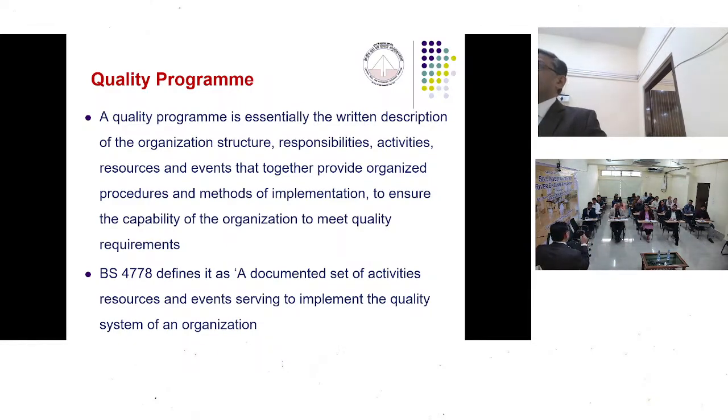At that time you are not going to consider that 1.76 or 1.75 or 1.77 are the same. Therein you are going to stick to a value. Value means value. If 98% density is required as per the quality manual, you will stick to 98%, not 97.8%. Because this 98% in itself has some inbuilt percentage of error, and if we err on the error side of it, then we are really going to compromise on the quality.